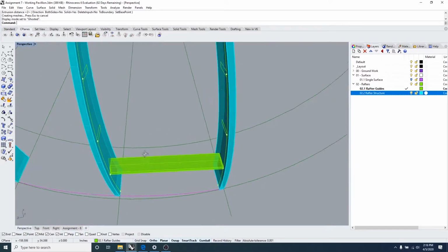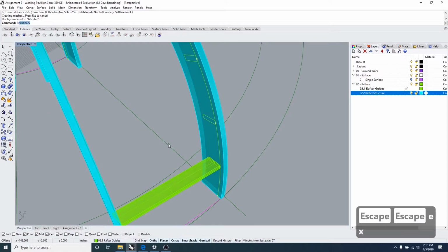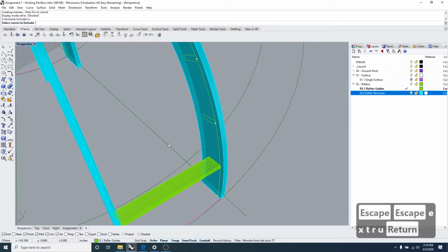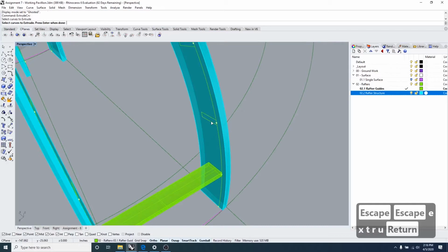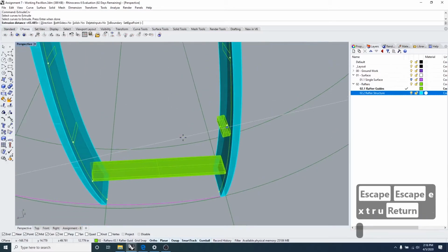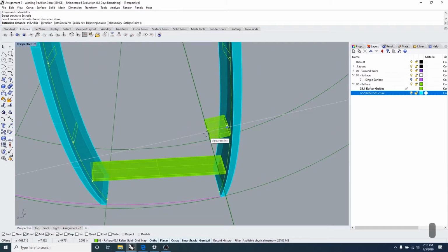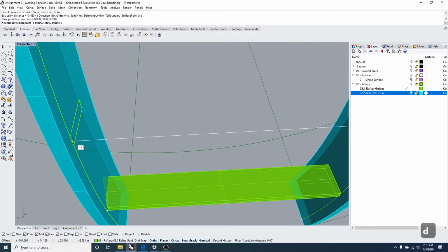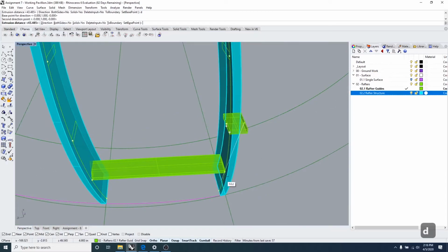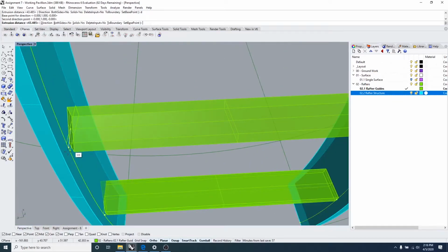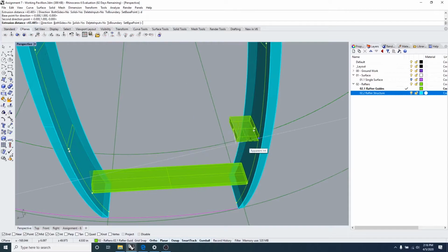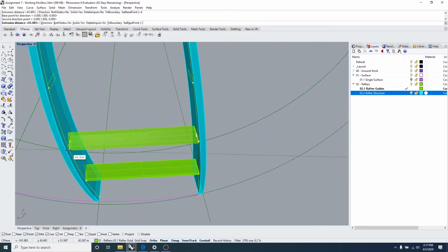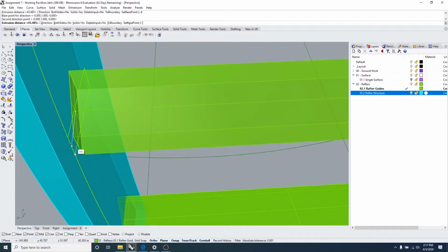So one way to fix that is by doing the extrude curve, picking the extrude curve. The direction is going to be the beginning of that point to the ending of that point. We don't necessarily have to draw the line because we're going to get prompted what the 2 points are, which we can just pick from the points that we already have on our guides.